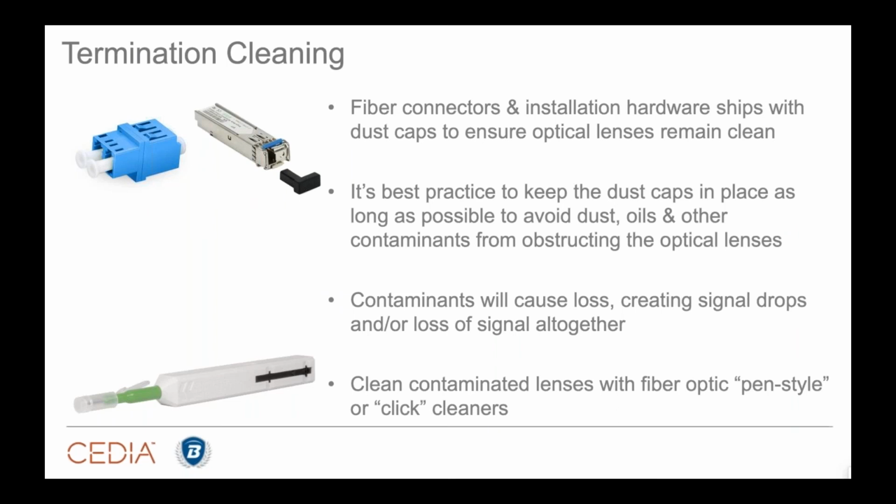Why? Well, think about it. We're dealing with lasers, light. We're dealing with waves of light going through an optical lens. And if there's anything blocking that from happening, we will have loss. We'll have disruption of those lasers. And in the networking world, it leads to packet loss, lower speeds. In the video world, catastrophic failures, right? Loss of video. It is incredibly important to keep dust caps in place as long as possible.